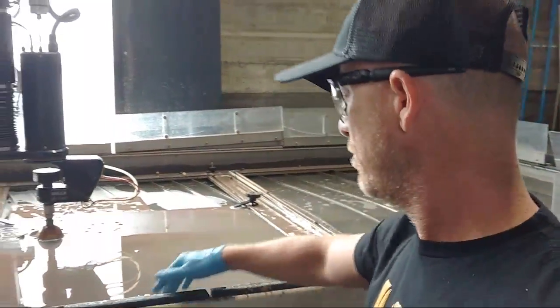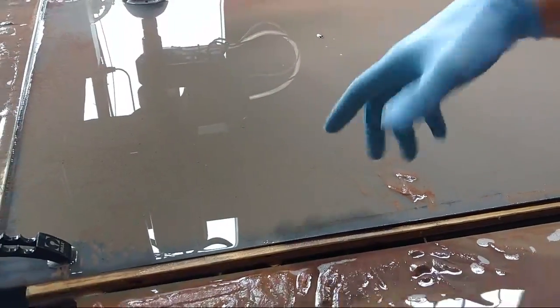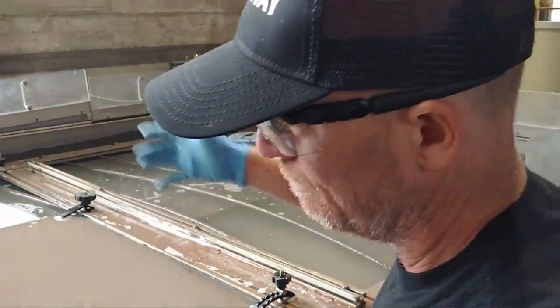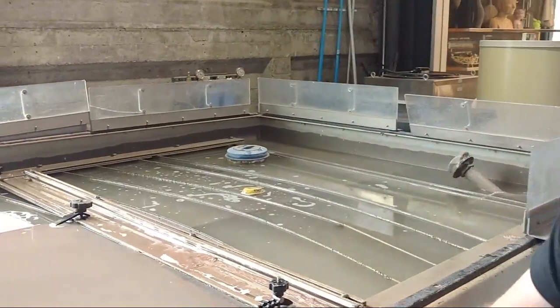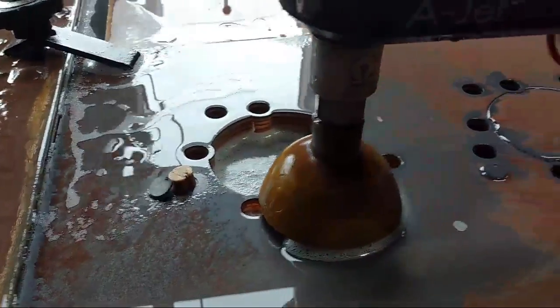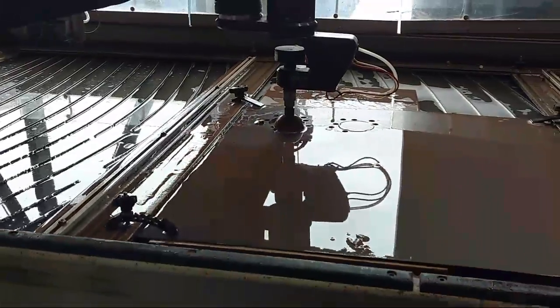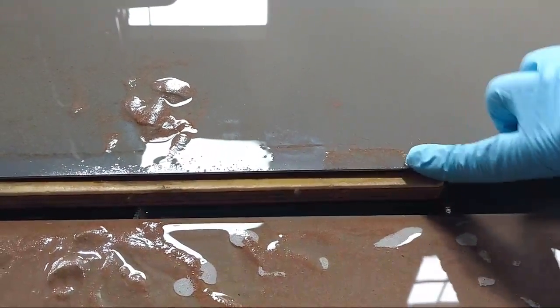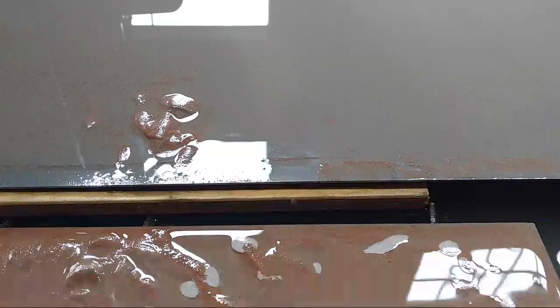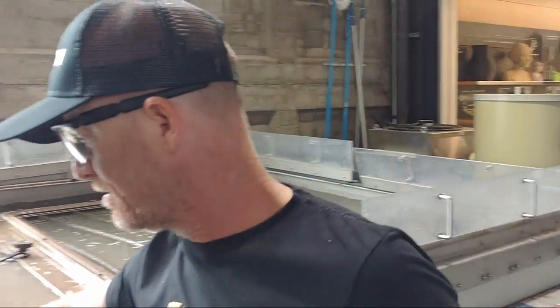Yeah, one thing I did, you'll notice here, I put some plywood underneath it because when the jet goes down into the tank, it creates an upflow and it would mushroom this. It would pop up in the middle. Okay, so I see that. So you actually see it cutting through the part? Correct. Through the wood, a sacrificial piece of wood. Correct. And there's a little bit of mushrooming happening still right in there. It wasn't like that when I first set up. I got another piece of wood under here as well. It's just smaller, you can't see it. I just got a couple pieces of scrap put under there.